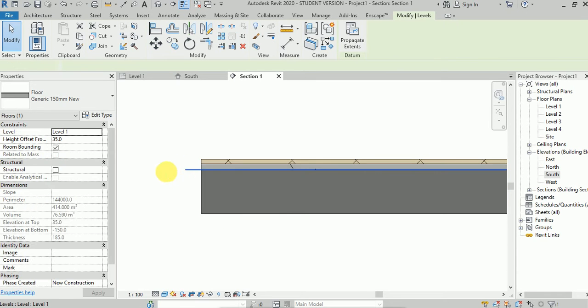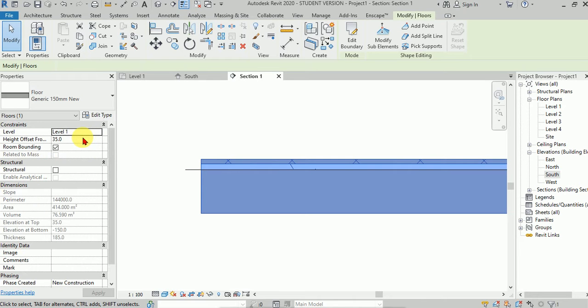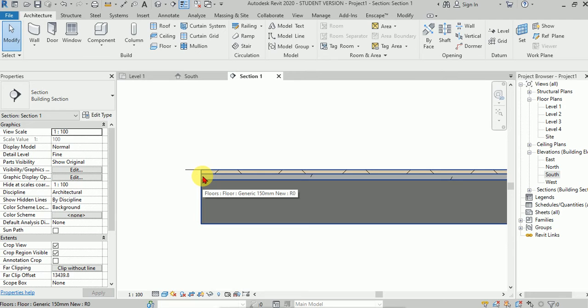Okay, if this is considered a structural slab. If it's considered a floor finish, you'll have it as a default one. Now in a BIM environment, if you have architectural and structural as separate models, your structural model will only consist of this floor, whereas your architectural model will only consist of this floor. So accordingly, one of the two people will need to give an offset.